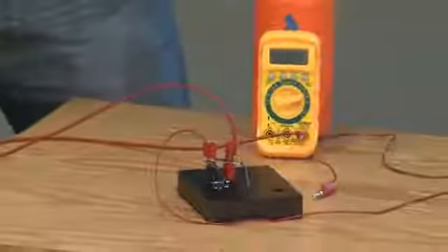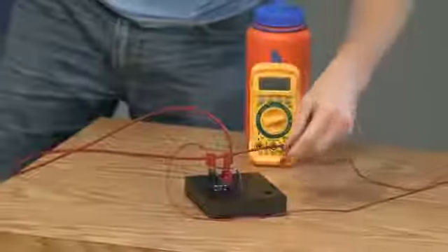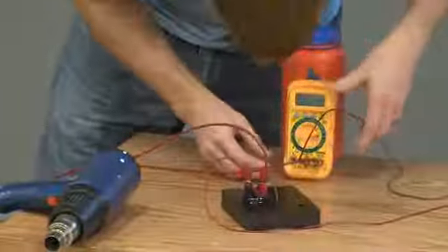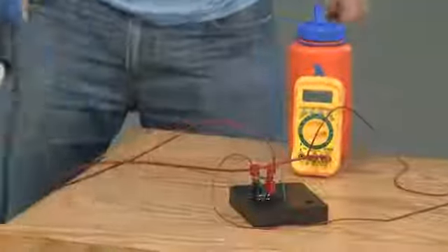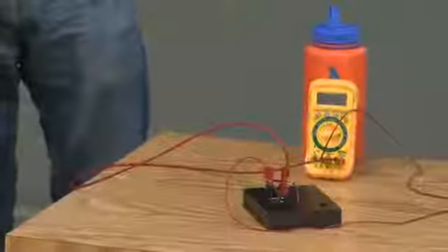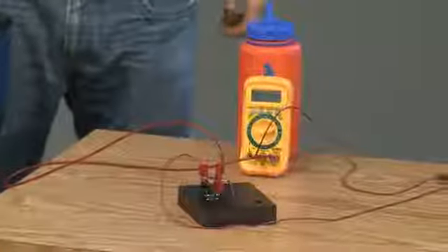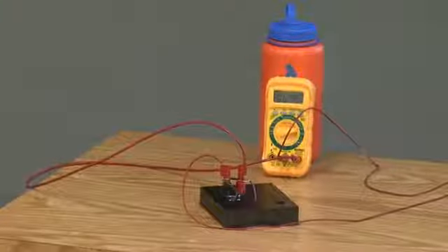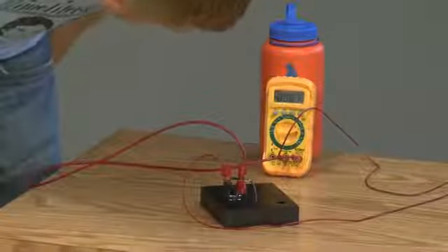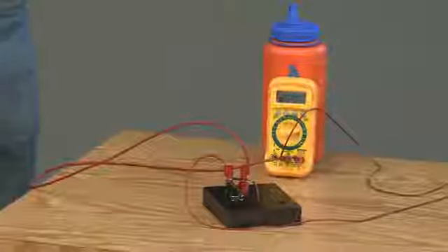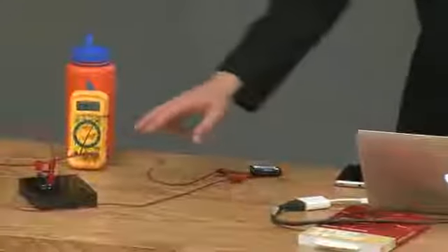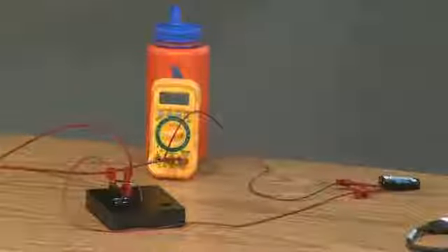A certain current will flow through it, and then Joe has a heat gun. He's going to heat up the silicon and see what happens as the Fermi-Dirac equation is affected by temperature. We should have an increasing density of carriers in the conduction band. Can somebody read off what the current is measuring on our current meter? It's about 9.8 microamps right now. So this 3 volt battery pack is forcing a current of 9.8 microamps across that little slab of silicon.